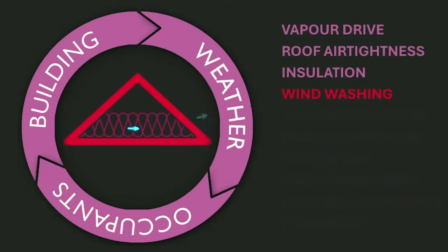Although this issue is more prevalent with permeable fibrous insulation, it's worth bearing in mind that simply friction fitting rigid vapour and airtight insulation boards between structural members may not be convection tight. If the joints and interfaces around rigid boards are not sealed and tolerances tightly controlled, there may still be gaps allowing both wind washing and convection-driven airflow around the board, reducing thermal performance and introducing additional moisture loads which may not be accounted for in the hygrothermal design.